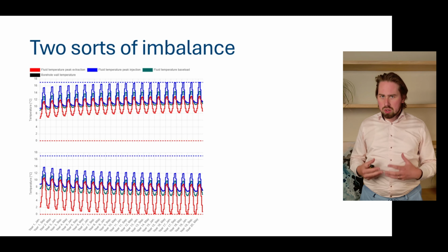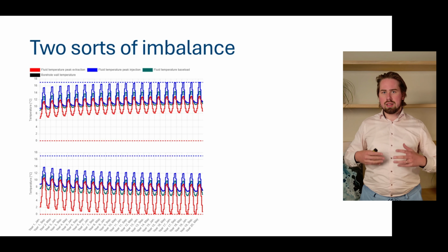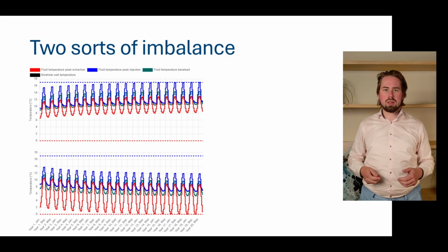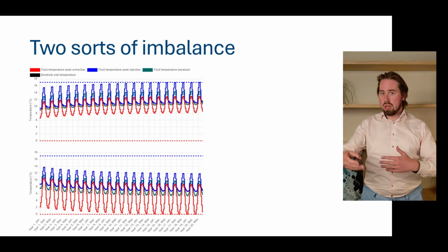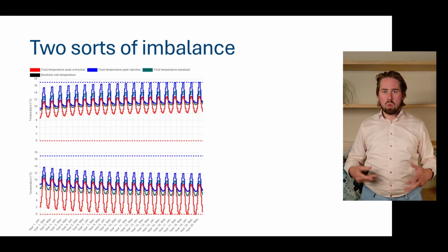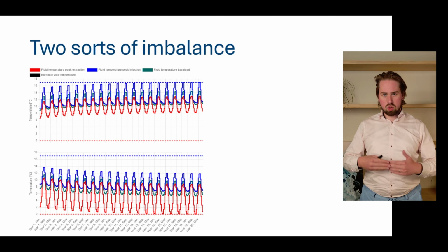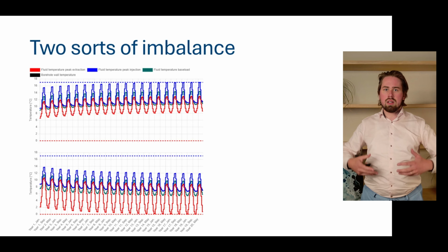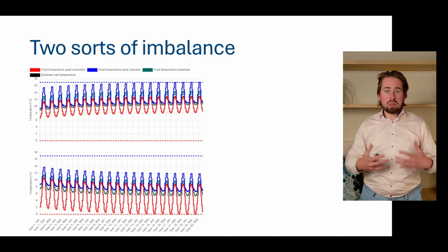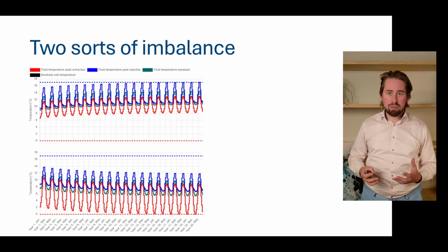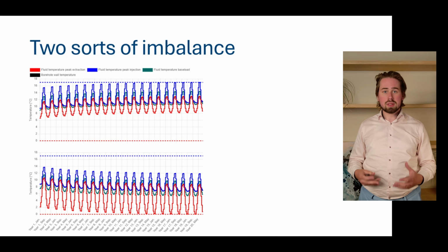And we do not want this imbalance because it drives up the investment cost. Because if your ground cools down or heats up year after year, we need to make sure that our borefield is sized in such a way that it can cope with it, that over the whole simulation period your temperature stays within certain limits. So it's better that we don't have this imbalance, but since it's a fact of life, a given for your building, we need to find ways to cope with it in the design.